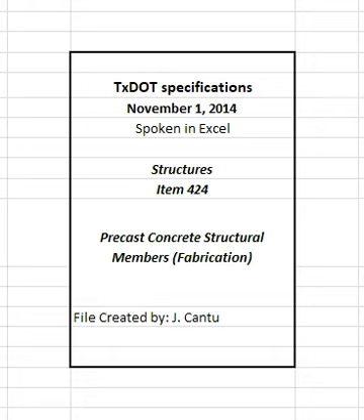Forms may be removed at the discretion of the contractor at any time after the concrete has reached sufficient strength to prevent physical damage to the member.